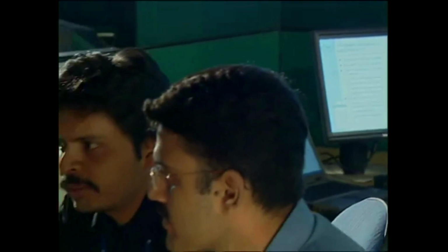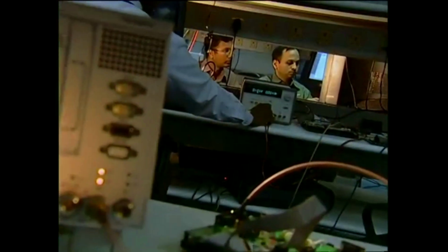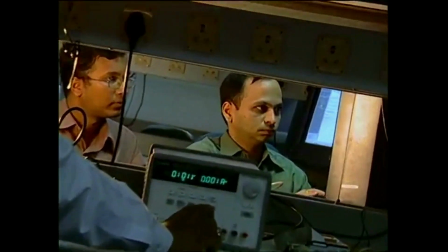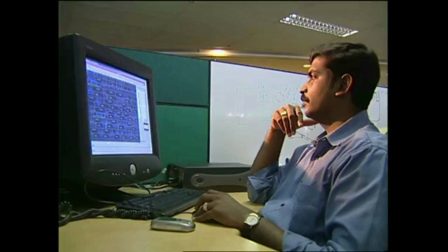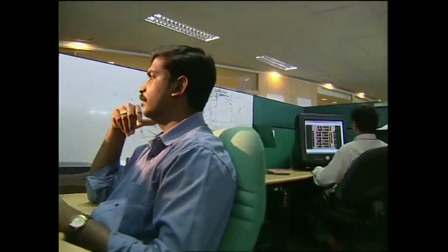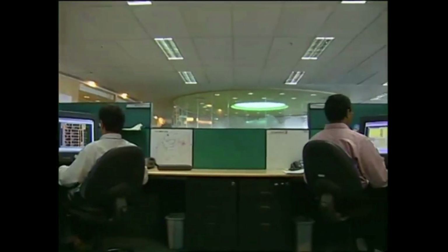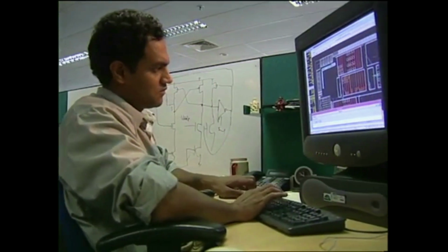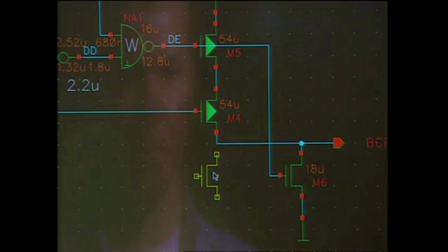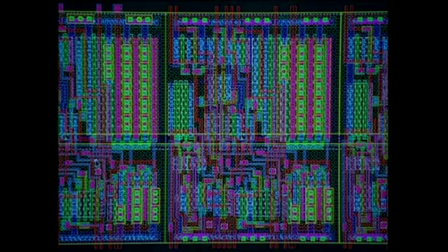Layout designers are at the beginning of chip manufacture. The large number of components calls for an elaborate design process to define the circuitry functions of the chip. Next, the technical and physical characteristics of the chip are simulated. Up to 1 billion transistors per chip are connected with the aid of wiring tools. The design tool forms the connections into a 3-dimensional architecture of sandwiched layers. This construction plan is transferred to masks. These are reprographic stencils for the subsequent manufacturing process.